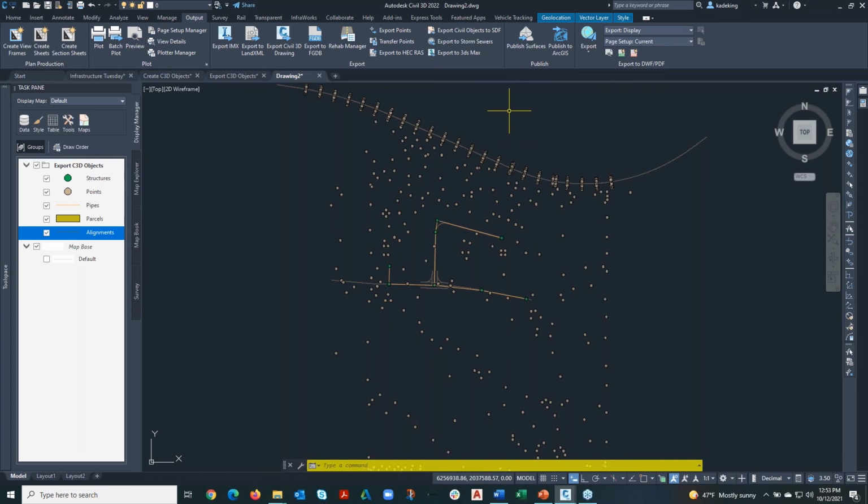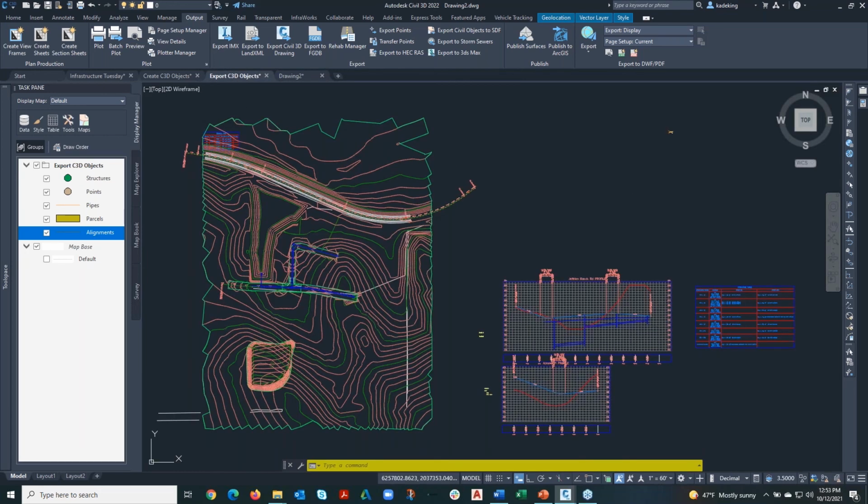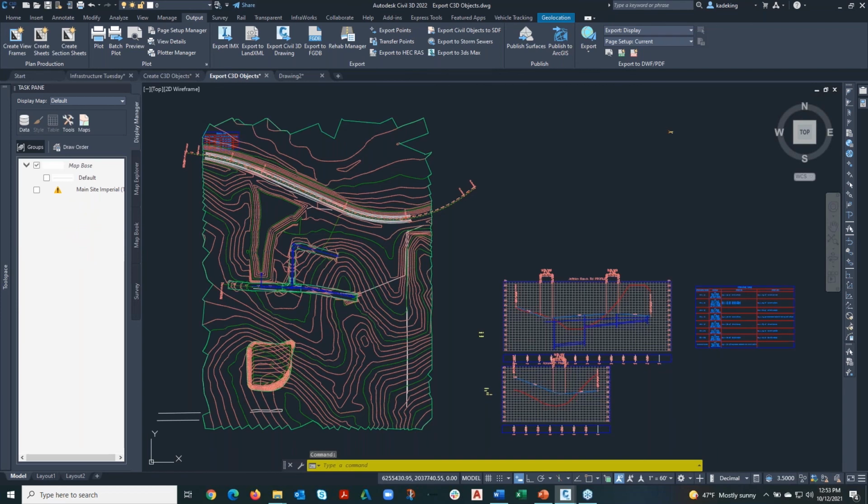Certainly, though, it is possible to convert SDF to shapefile data. We have nowhere near enough time for me to show you how to do that, but AutoCAD Map can do that. It can bulk copy, and that is the term Map uses. It can do a bulk copy from one type of file to another. So I could create a new shape file and bulk copy all of the SDF data into a shape file. But like I said, your GIS people will be able to use it in SDF. So anyway, that just gives us a little bit of an idea of how that works.